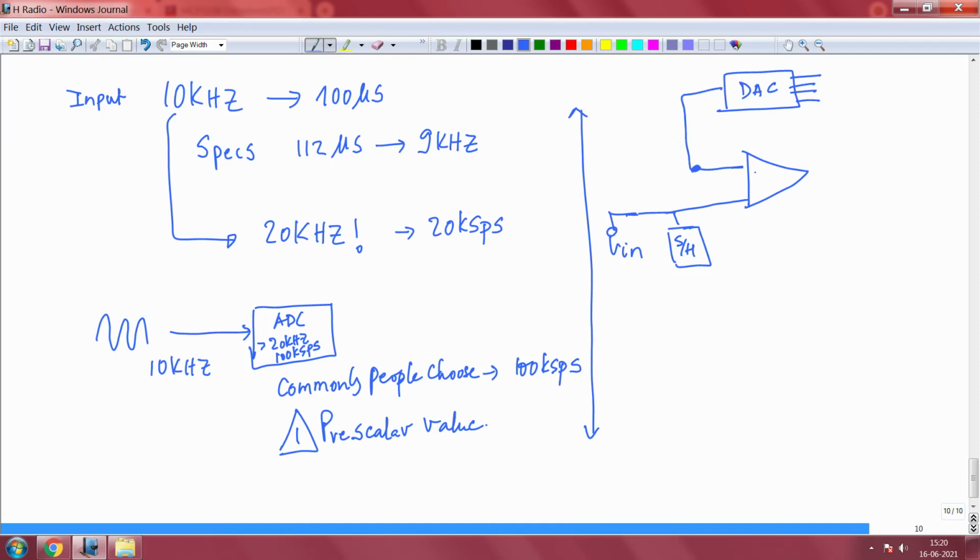How it starts is, let us say you have a 4-bit ADC, it will first put 1 in the MSB, 0 0 0. Corresponding to this 1 in the MSB, some voltage is given, and then it will check whether this will give you a 1 or a 0. Okay. Now a comparison actually happens in this comparator.